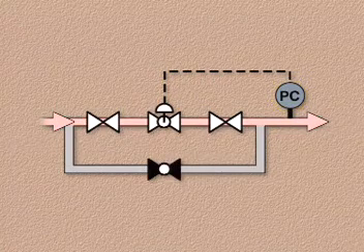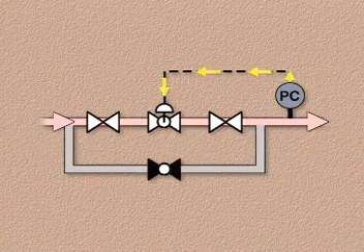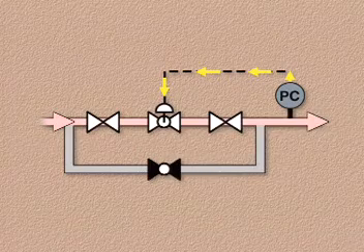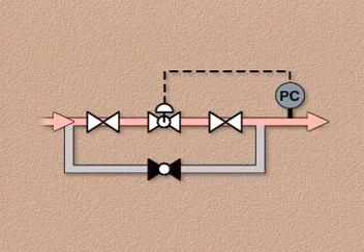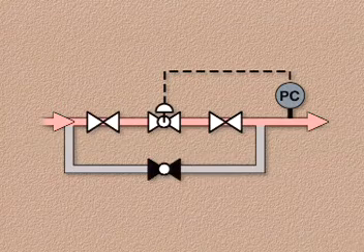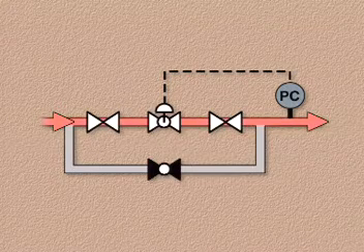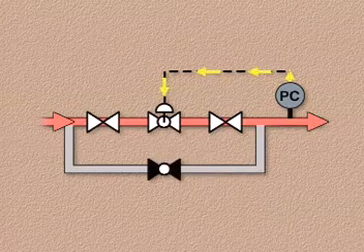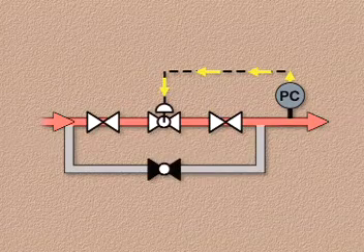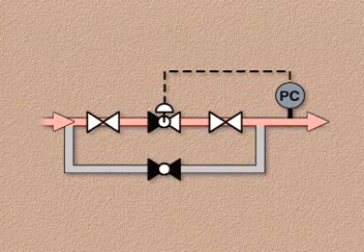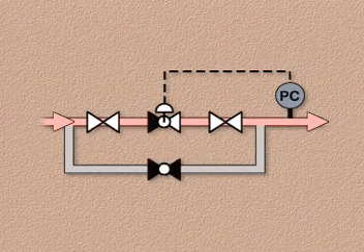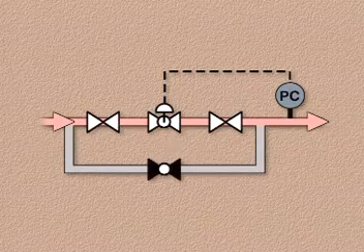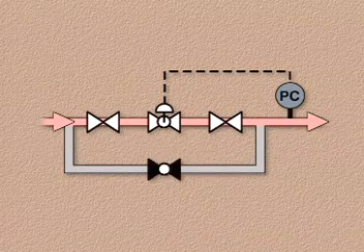The valve is connected to a pressure controller that monitors steam pressure in the downstream piping. If pressure decreases below the set point, the controller sends a signal to the valve operator to open the valve to allow an increase in steam flow with a corresponding increase in pressure. If pressure increases above the set point, the controller sends a signal to the valve operator to close the valve enough to decrease the flow of steam with a corresponding decrease in pressure. The valve operates as necessary to maintain pressure within the design range of the system.